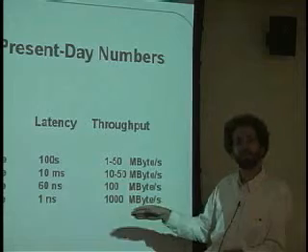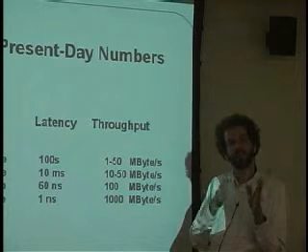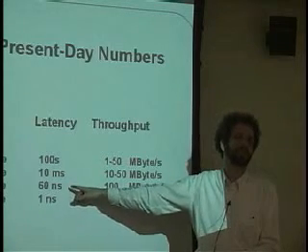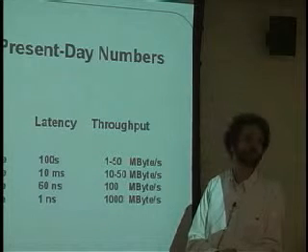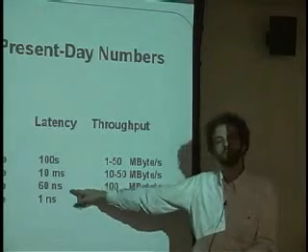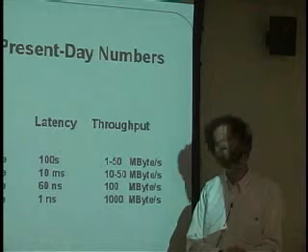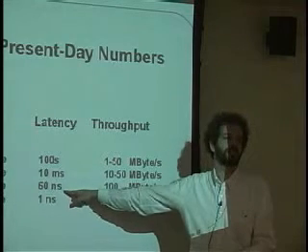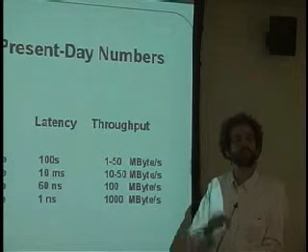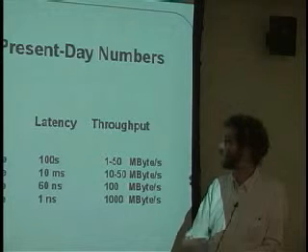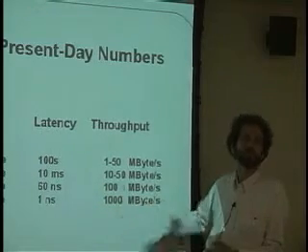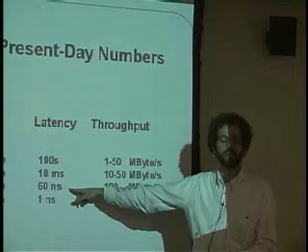That's true, but keep in mind that the DRAM itself is heavily pipelined. It still has a latency to get the first word of 60 nanoseconds. They don't talk about that when you buy it, but it's true. What that means is that if this were used to implement the register file, we'd be in trouble, because our machine is running maybe 60 times faster than this. Every time it wants a new location in the DRAM, some random new spot it hasn't accessed before, it has to wait 60 clock cycles to get it. Never mind that it clocks out much faster than that once it begins to go. The latency is very long.